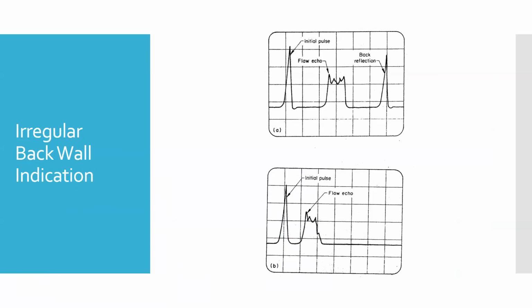And what's happening with corrosion isn't always perfectly symmetrical, right? If we have a part, and when we're finding corrosion, usually it's the backside. A common feature of finding this, we looked at it with eddy current testing as well, is if we have, say, two pieces of aluminum that are riveted together, and we want to see if there's corrosion between the two of them without taking them apart. So if we have a piece of material and it has a corrosion area that looks like something like that, that's where you're getting the irregular back wall or the irregular echo like that.